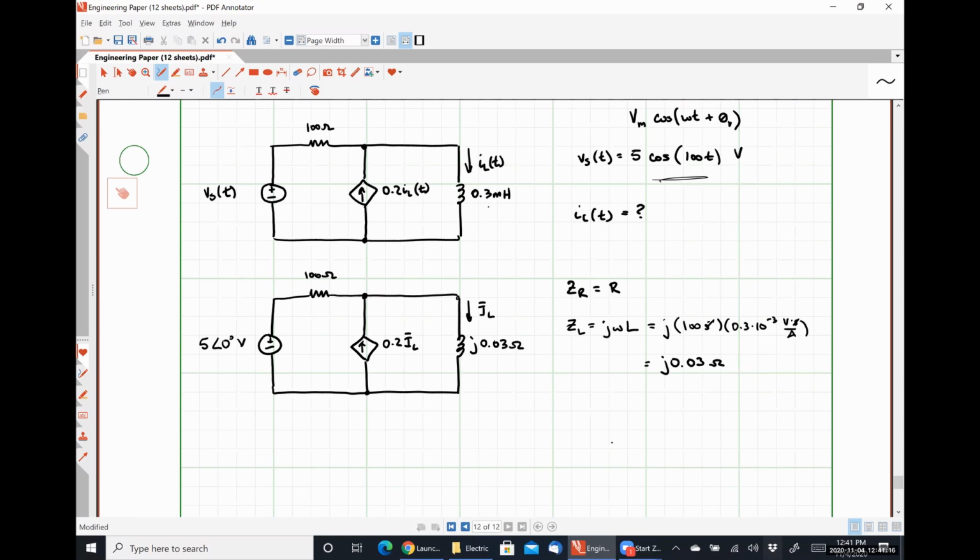I believe you had suggested using nodal analysis. Okay. I both agree and disagree with your statement. Here's why I disagree with it. Nodal analysis implies that we're going to set up multiple Kirchhoff's current law equations here. And if we set up a system of equations, again, I cannot emphasize this enough, your calculator literally cannot do them with complex numbers in them. So we are avoiding systems of equations like they are the plague, okay? Yes, KCL is more in tune with what we could do.